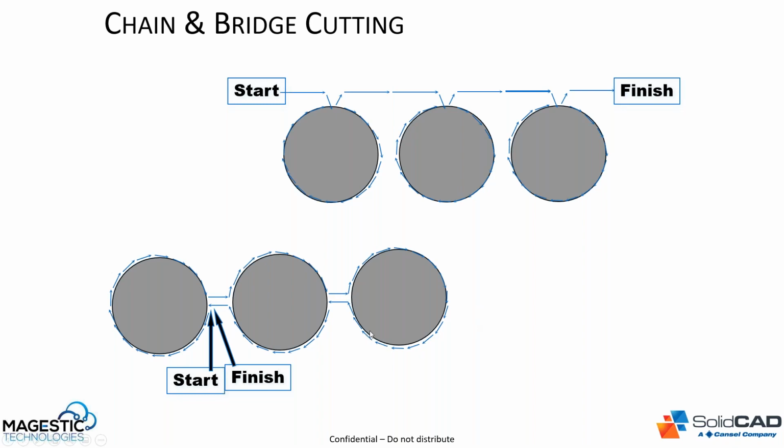This allows us to gain material utilization and nest parts closer together, but with any of the bridges between parts, essentially you're combining 3 parts into one. So if this part ends up tipping up, or somehow the quality is sacrificed, you've sacrificed 3 parts instead of 1. So it really depends on the processes that you use in your shop, which methods and which optimizations would work well for you. But we do support all of these different types.